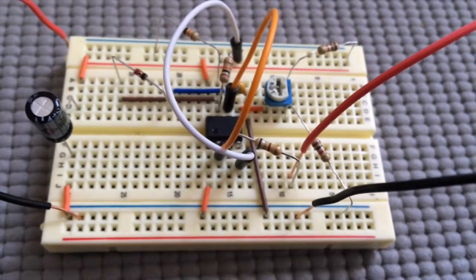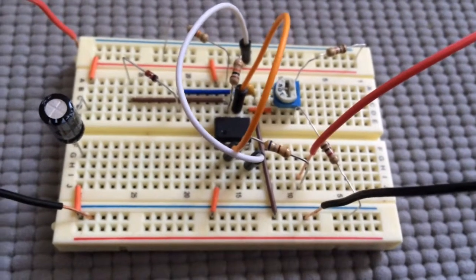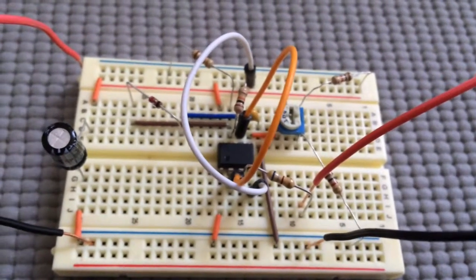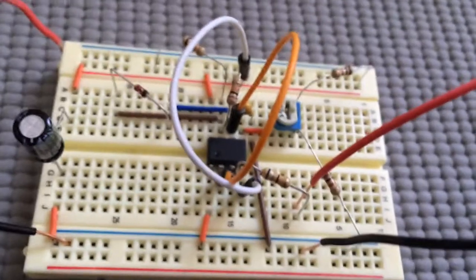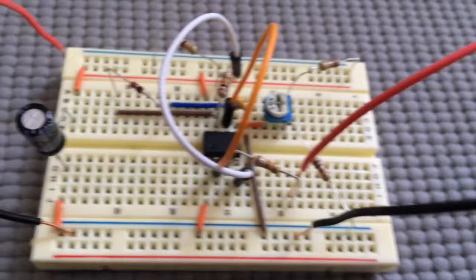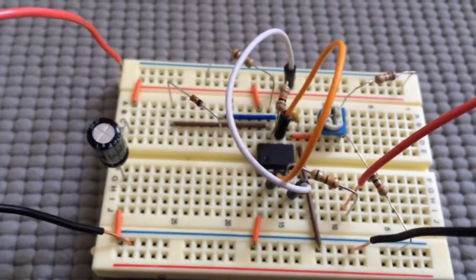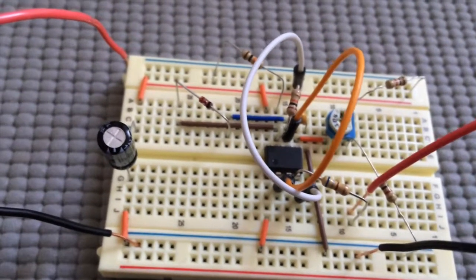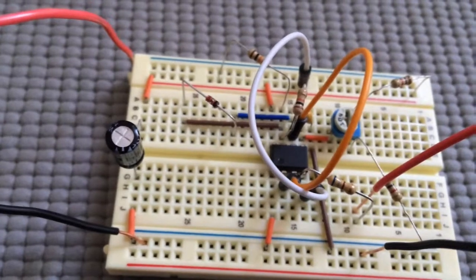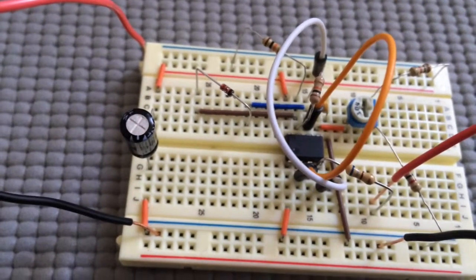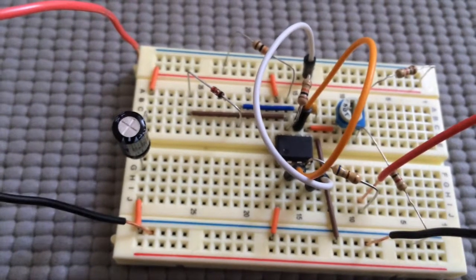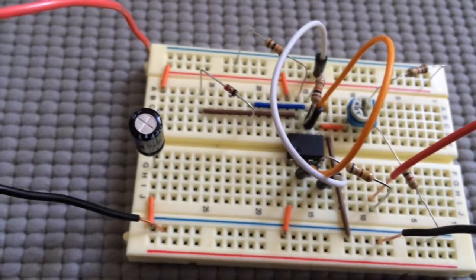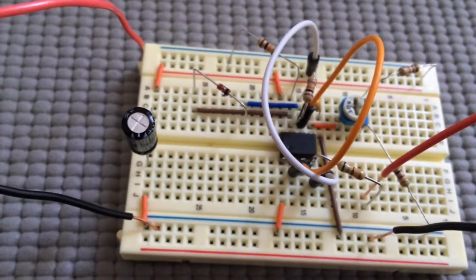This example will be used to investigate the behavior of controlling the voltage across the threshold pin of the 555 chip. In its typical default configuration, the threshold pin is grounded through a capacitor, and the default threshold voltage is 2/3 the applied voltage. But if you vary the voltage across the threshold pin, it changes the threshold voltage required to turn off output.